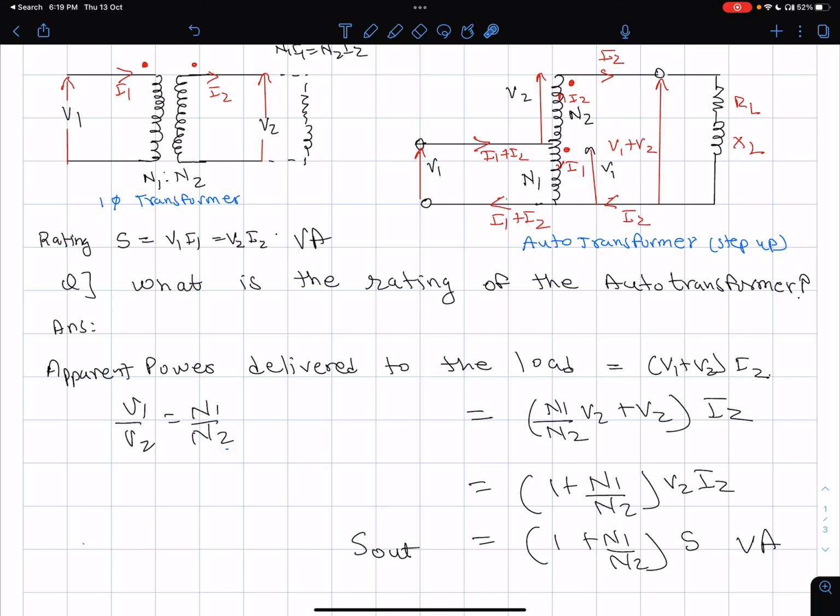It also means that the efficiency of the transformer goes up. There is only one cost which we had to pay for it, remember. In the normal single phase transformer, the two windings are electrically isolated. So you can have a 1:1 transformer, for example, just to create electrical isolation between the primary and the secondary circuit. The only coupling is that of a magnetic coupling.